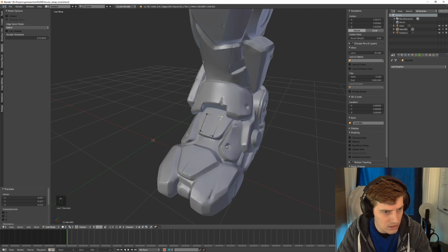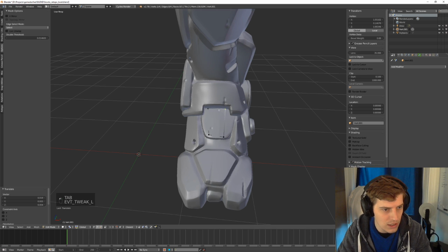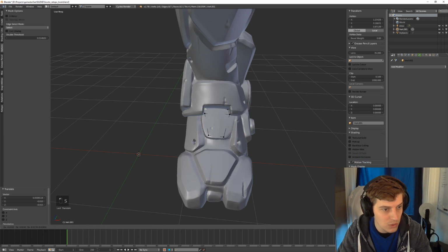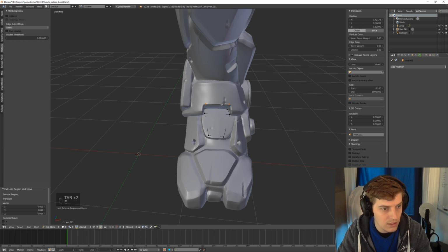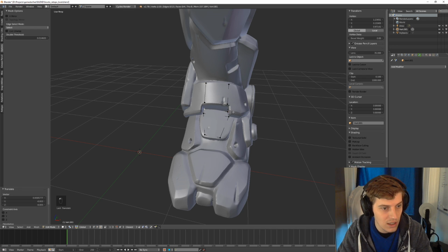Okay, right, let's start retopologizing. I'm not going to retopologize the whole thing. I'll just go over the basics. What I usually do is switch between edge and vert, or I enable both of them, and then I can work on both. So I select the edge, I extrude by pressing E, position all my stuff, extrude again. Oh, sorry about that. Extrude again. Extrude again. So there's a lot of just extruding and tweaking stuff.